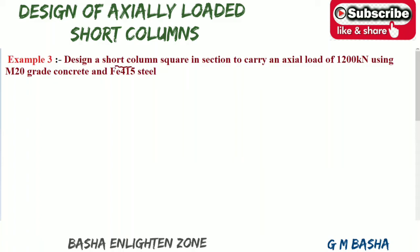In this lecture, I would like to explain another important example which is based on the short column. See here, this is example 3. Design a short column square in section to carry an axial load of 1200 kilonewton using M20 grade concrete and Fe415 steel. So first write down the given data. What are the data which is given in the question?